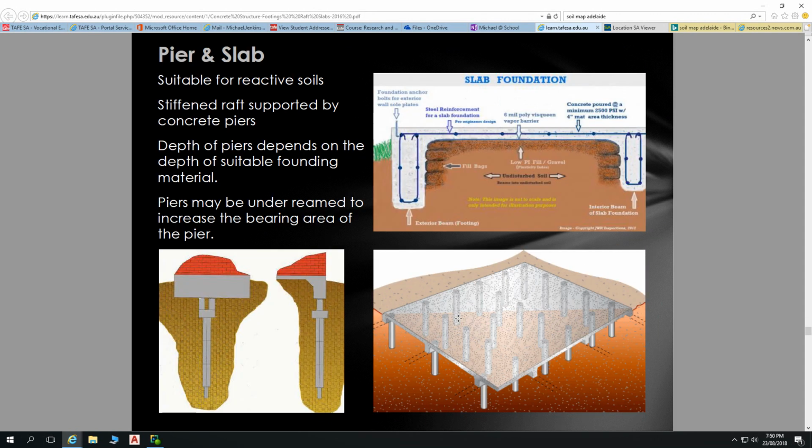But it's not hard to get a site within 10mm variance like soil, even with a crusher dust that's got like a 3mm aggregate. You can screed that off. In fact, I've installed a lot of really big tanks on flat pads, and some places I've worked, there's been basically next to no variance, like 5mm from one side of the tank to the other, and these are very big tanks that will take up this room size.